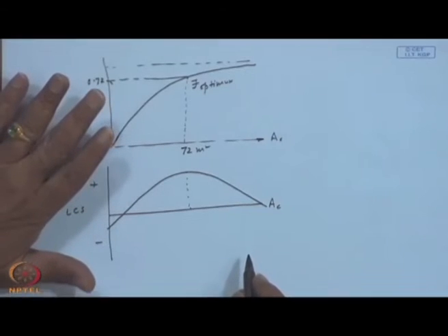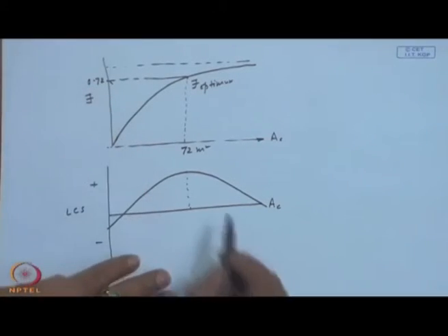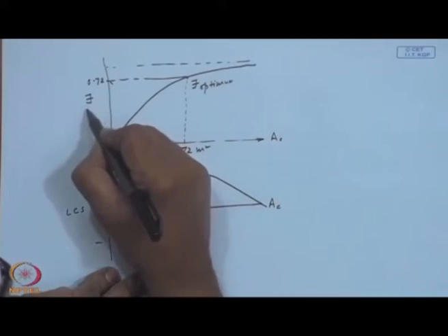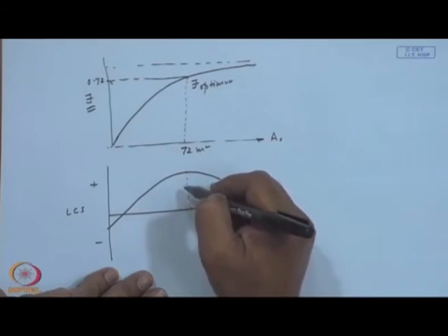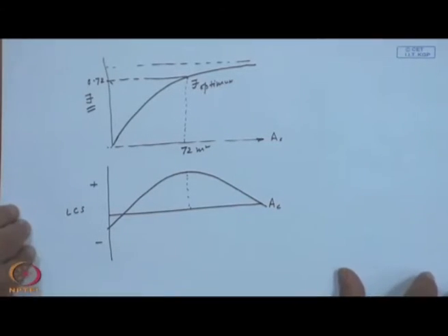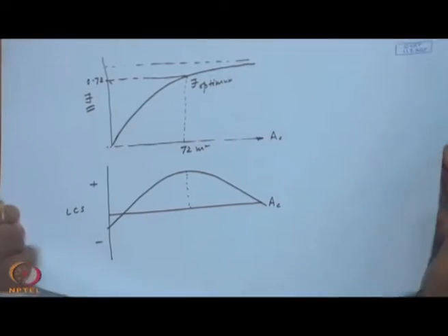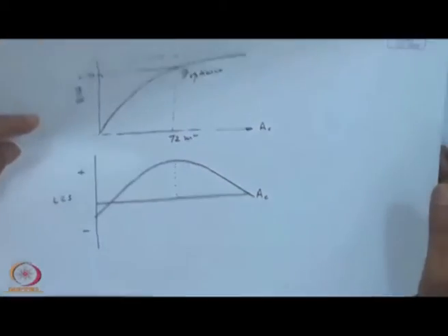One thing this is propagating is, you do not need to aim for a 100% solar load fraction, but you aim to maximize life cycle savings, because initially some subconscious feeling is to show that solar can do everything, but I think wisdom prevails, and the objective is that it is not a substitute. You do not want to replace one energy source with another energy source. You would like to utilize where it is best.